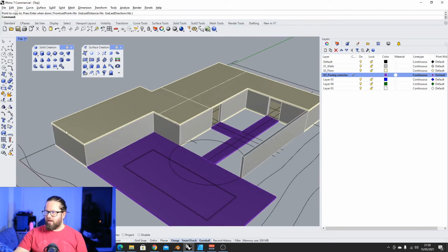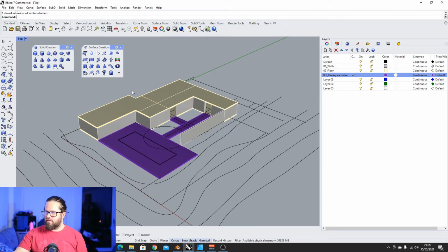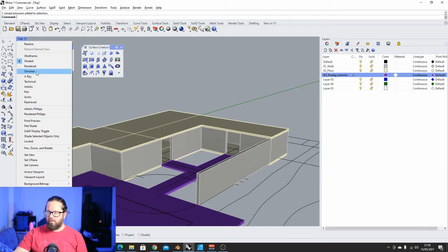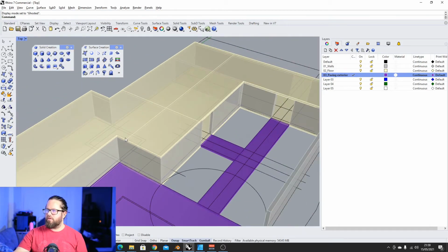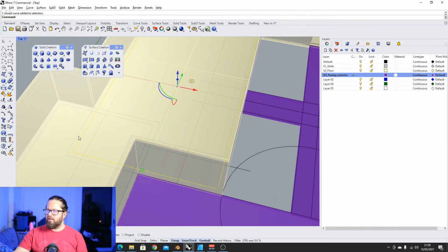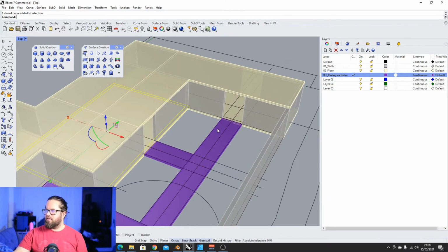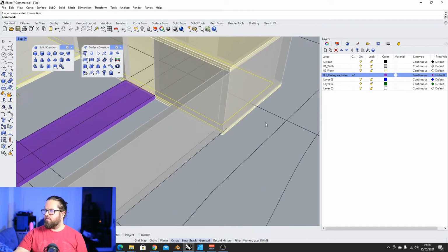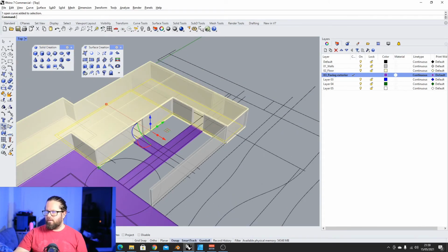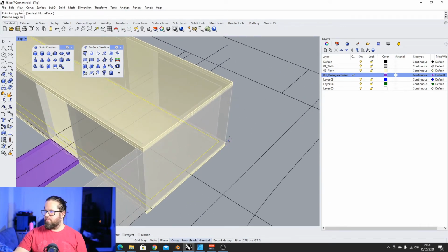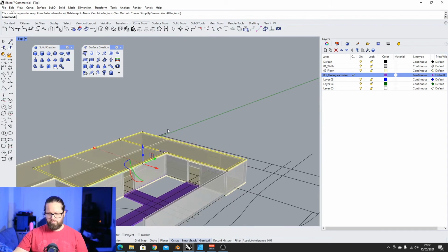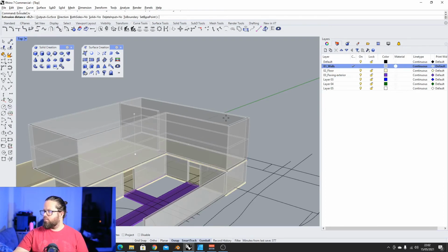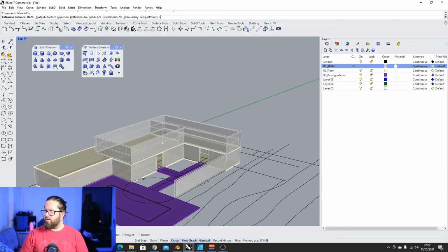And so now I'm thinking actually this is going to be a terrace and this is going to be the second floor. So I could go into ghosted view, so I see a bit what's underneath, and I could take these lines here and these ones, and also bring them up, copy them, and then extrude and make this the walls, and it's also 3 meters.